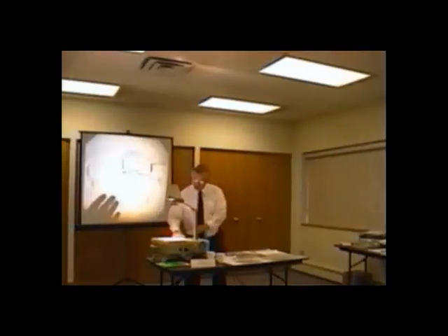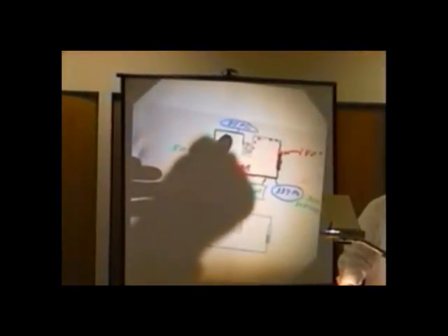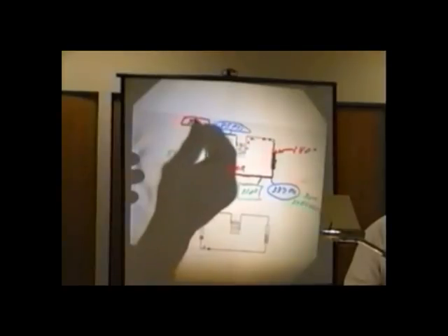Okay, makes sense? How can it get colder when I'm raising my pressure? And let's go back here to the chart. How can it get warmer when the suction line is full of liquid? Pressure goes up, temperature goes up. But now, I already got a little bit of BTUs over here being absorbed by that vapor. So I'm going to put my thermometer on it.